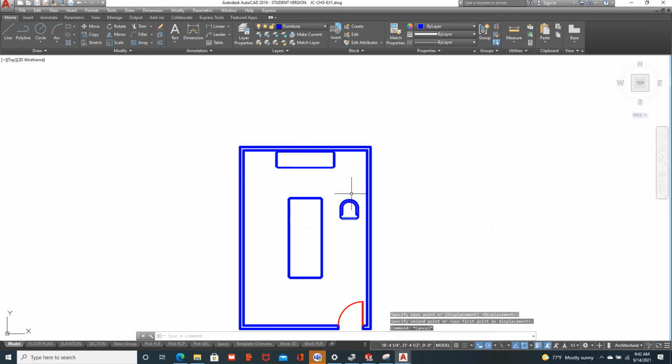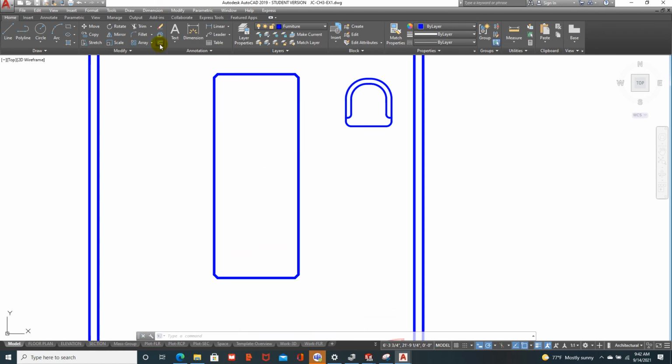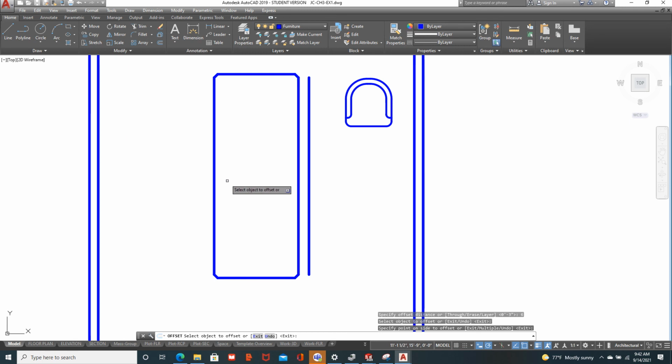And then what they do is they offset the table line. And it looks to me, let's see how much it's offset. It looks like 6 inches. I could be wrong. But if I come over here and I say offset and I say 6, now if it offsets the entire square, then it's a rectangle and it's a polyline. So you have to fix it by exploding it.